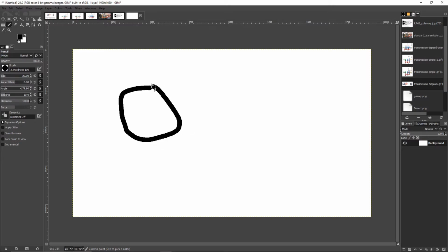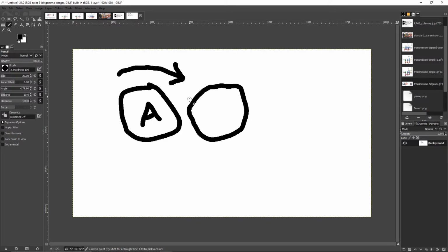So we've got gear number A, and it's rotating this way, right? Well, that's cool, but because there's only one of them, we don't have any gear ratio going on. So we need to mesh a second gear to gear A, and I was supposed to draw that as a different size, so this makes sense. So we have a different gear here, and these two are meshed together. And because they're different sizes, we're going to achieve a gear ratio of whatever, right? Which is the whole purpose of this.